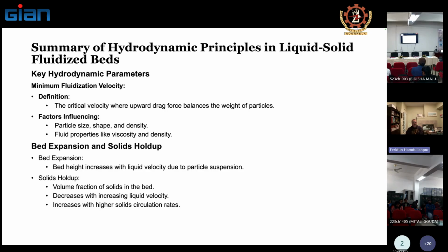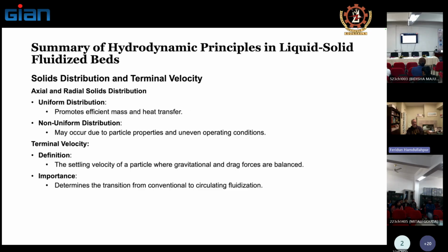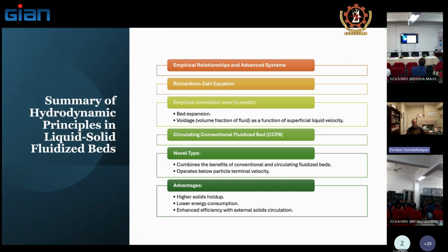Solids holdup, you need to figure out so that you can successfully calculate your mass transfer in this case. Solid distribution, again, mostly it's uniform distribution. You have to have a very bad design to have non-uniform distribution of these particles.